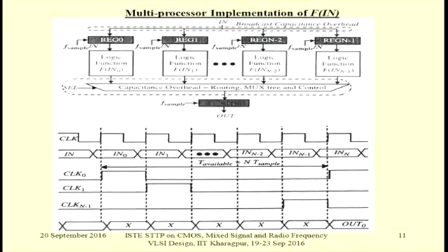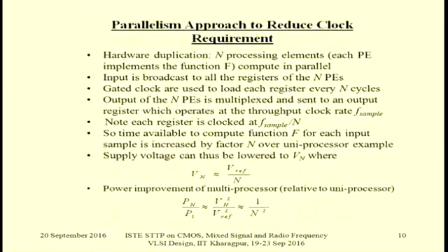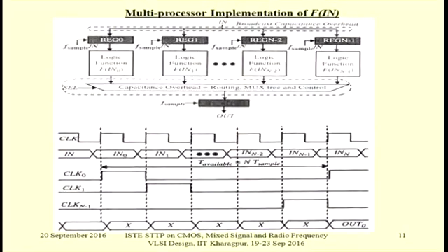That means, say, consider that we are doing some matrix addition. So the first row of the two incident matrices are obtained from two parallel registers, okay, and are latched here. Similarly, next the second values will be obtained here. So there is a skewing of the clock. This skewing of the clock is obvious from this. So clock 0, clock 1. Okay.